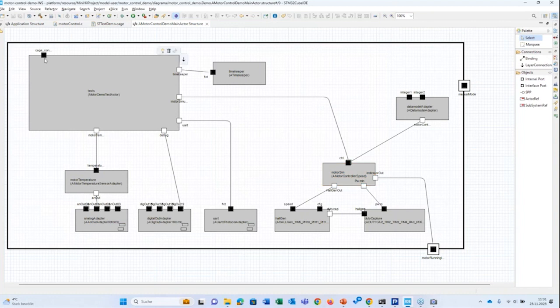So now the third thing I need is the test case. So here is the test case. The test case either directly connects with the system under test over UART or the temperature simulation, or connects with the motor simulation, because it's really hard to detect problems just based on PWM, but that's why I have the motor simulation here.